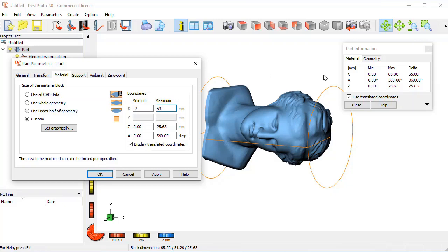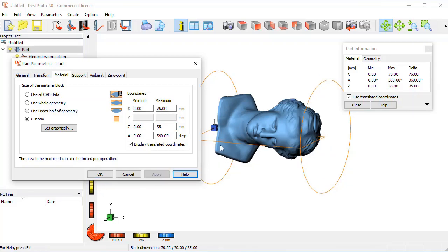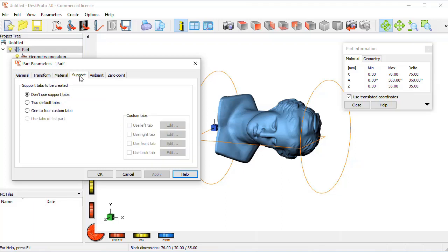Diameter of the block needs to be larger as well. My block is a bit oversized, it's also squarish, so I will increase that to 35 millimeters, to make sure that my cutter doesn't go too deep in the first layer. Here we are.